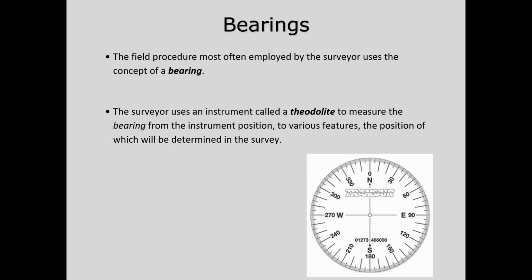In this session we'll be talking about a very important concept, the concept of bearing. Bearing is the engineering method that we use to describe the direction of linear segments. Segments such as the segment of a road, the center line of that road, or a segment of a pipeline, or a retaining wall, boundary. All of those linear components.